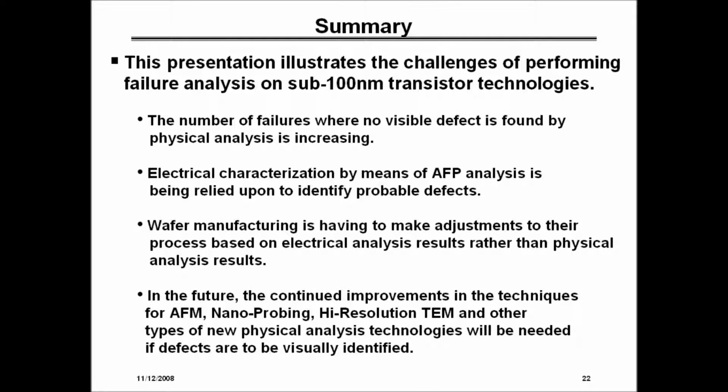The other thing that we found that seems to help is that when we polish down, and say you want to probe a via, you remove that overlying metal layer and expose the via, and you need to delineate that via. We found that it works better to use the RIE to remove a little bit of the oxide. It also tends to clean up the top of the copper, and it makes it easier for your probe tips to establish electrical conductivity to the metallization.